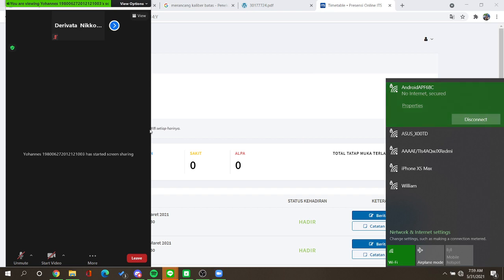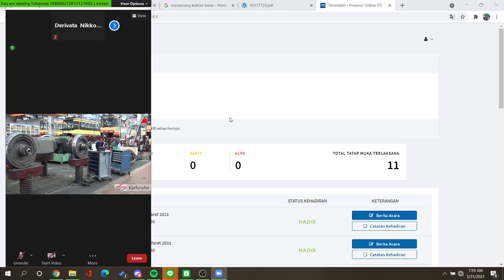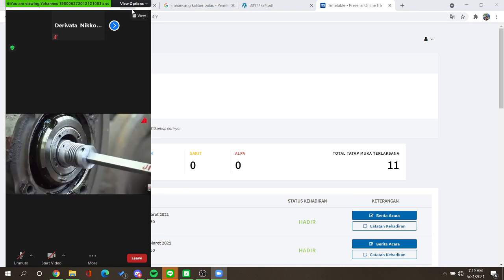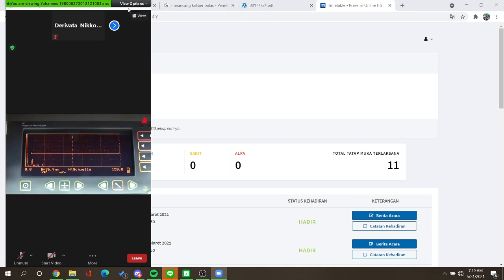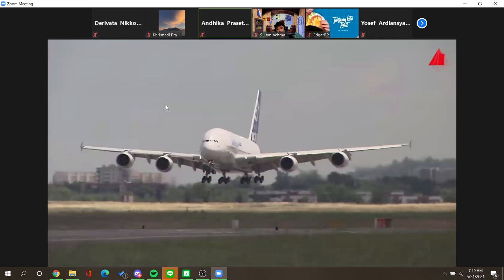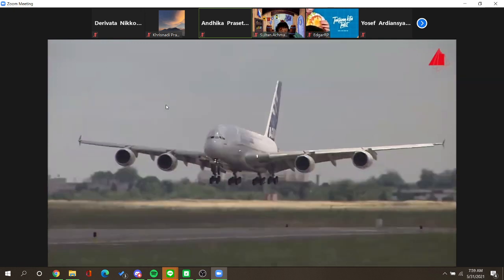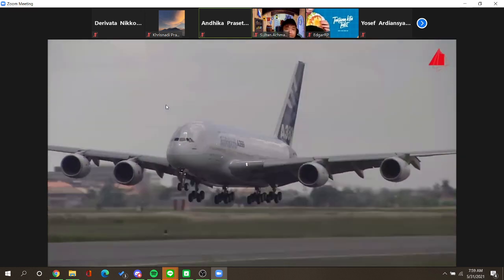has to go into the test hole at regular intervals. Experienced staff use ultrasound to examine special components, especially the wheel set axles, to check whether they are still in perfect condition. Aircraft are also inspected for fatigue cracks at reasonable intervals. This helps us to depart for air travel without worry and land again safely.